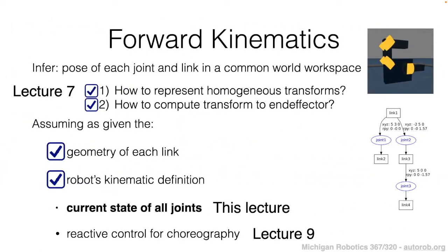So at this point, we have the ability to represent the current state of all joints within our forward kinematics and model the articulation that's induced by that current state of the joints. So we can put a check there. From the previous lecture, we know how to implement the forward kinematics as a matrix stack recursion, and now we've added on to that the ability to express these articulated joints within the forward kinematics process.